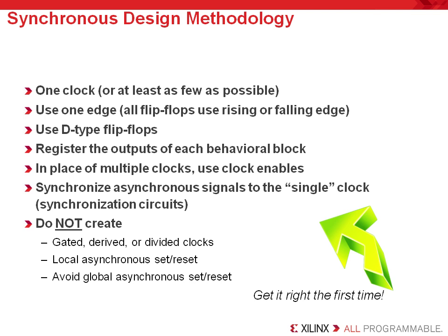Likewise, don't use asynchronous sets or asynchronous resets, especially in Virtex-5. Try to keep in mind that global resets are not necessary since the FPGA will power up in a known state. Following these tips may seem like more work, but remember that you are really going to be saving time from debugging your design later if it ends up glitching. If it does not glitch, you may be saving time from having to fix your finished product after the fact.